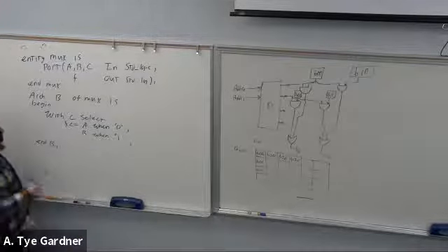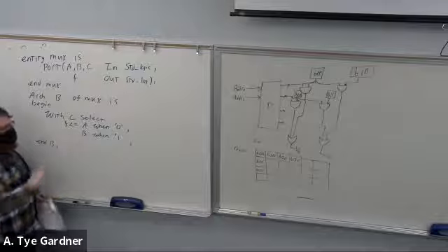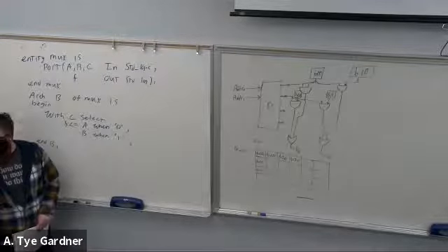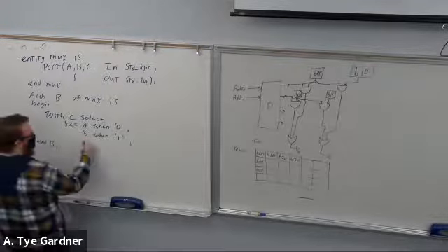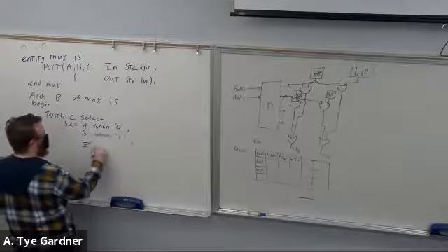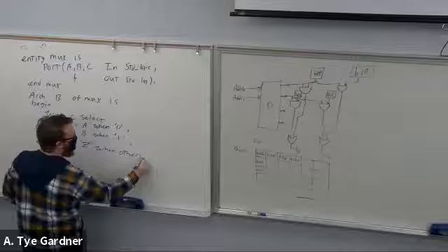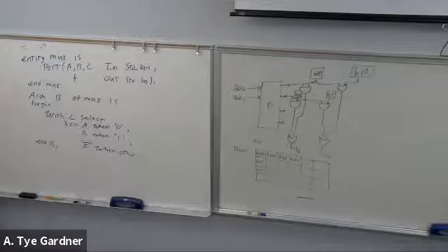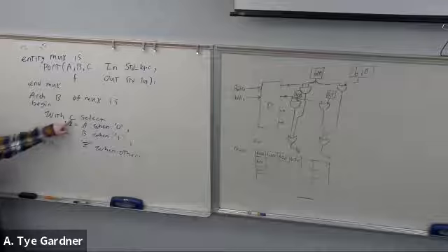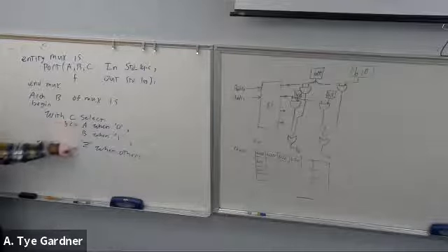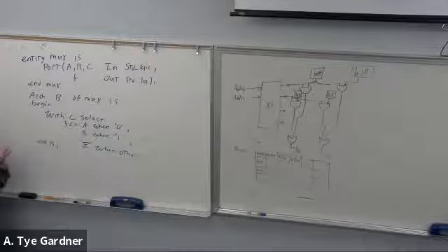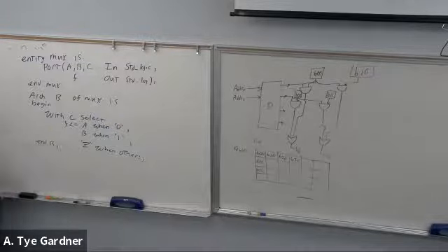So what that was saying is it's going to assign B if C was equal to Z, which gets hard to troubleshoot. So we're going to say Z when others. That way, if something goes weird with my C signal in my testing, my output doesn't go to B, it goes to Z. And that's a good indicator that, oh, something weird happened, right? It shouldn't go Z unless something happened. Helps you debug.